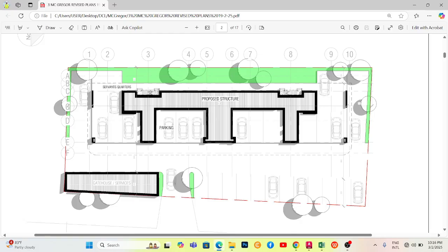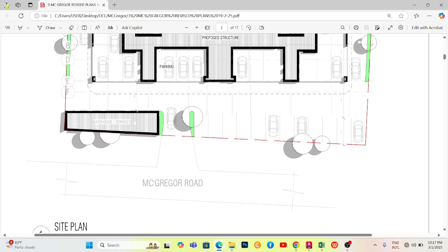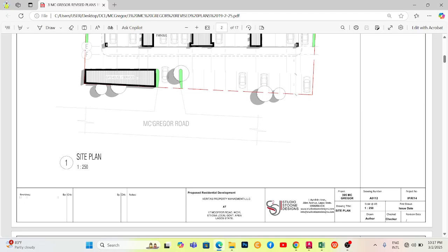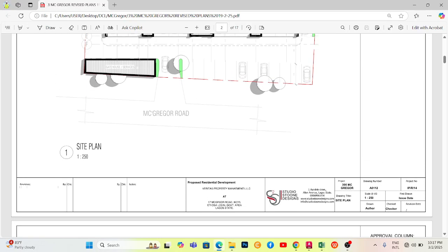So we'll just use the grid line for the building, for the proposed structure. The same grid line, we'll use it for the structural too, to superimpose both the structural and architectural together. So there's not much problem with structure when it comes to this aspect. So that is that for architectural drawing. That is the number one thing I always pay attention to.